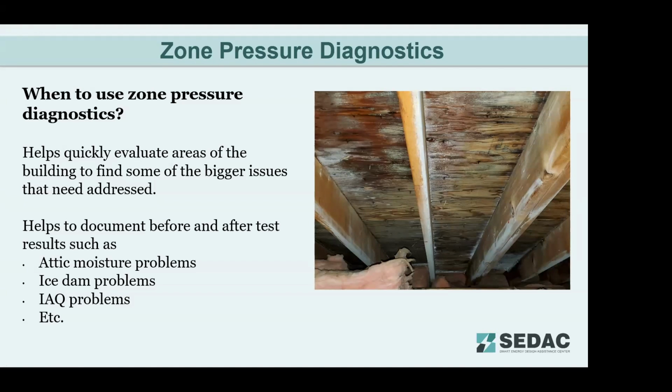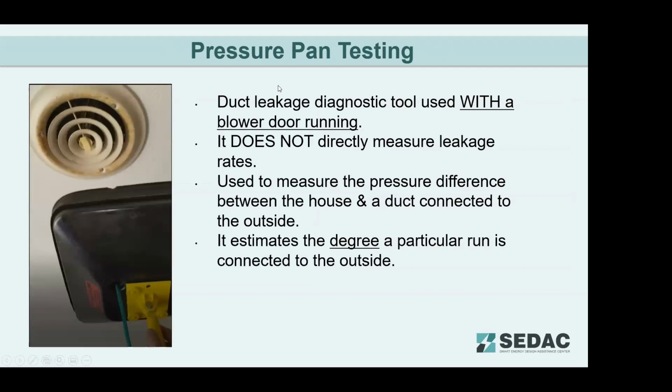Now, there's a lot that can go into solving that problem, but a lot of it is air leakage from the house into the attic. So we can use zone pressure diagnostics to figure that out.